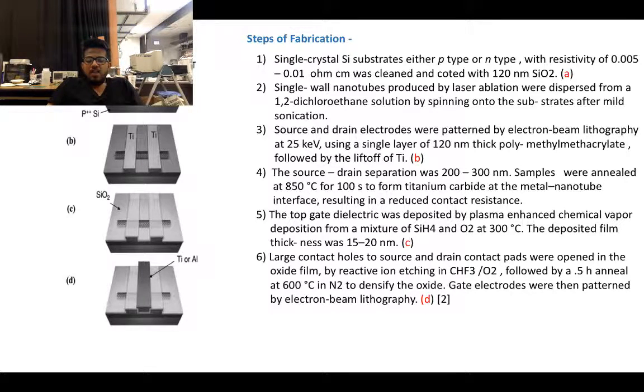So at the end, what you should get is something like D, this one, which is your transistor, and now you just need a contact probe or a two-point contact probe to draw three wires, one from the drain, one from the source, and one from the gate.